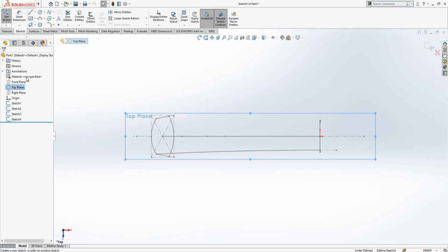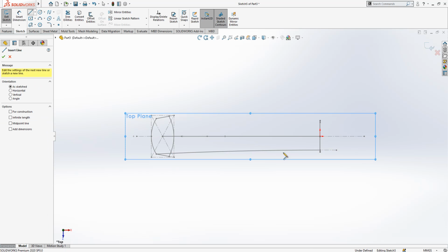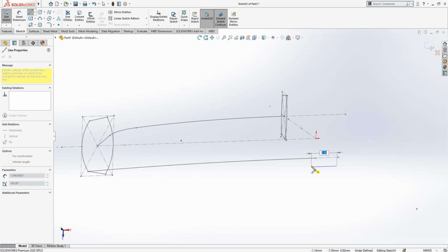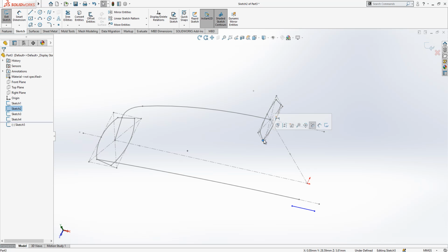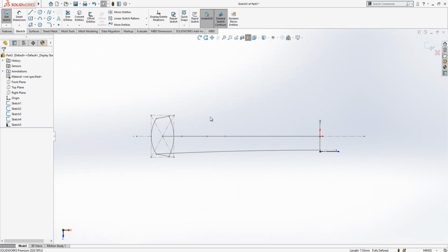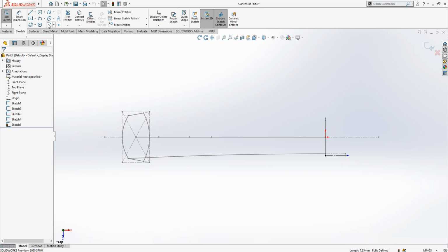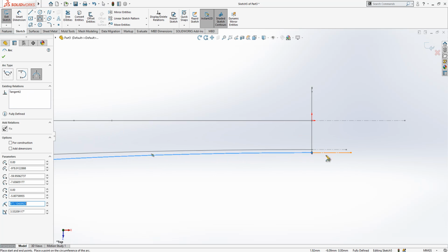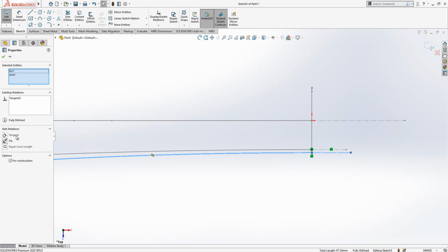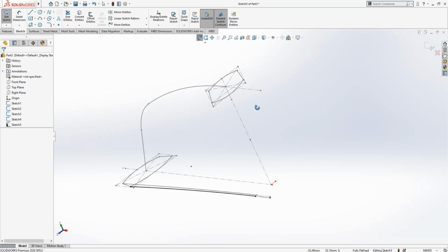Second operation, same thing again. Let's first fully define this point. Internal point. This point, in fact, sorry. 2 is selected, coincident. And I'm going to look from normal to. I select this point, make these two tangent. So 2 times.